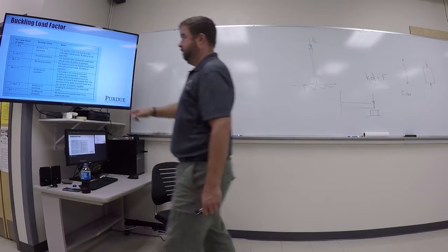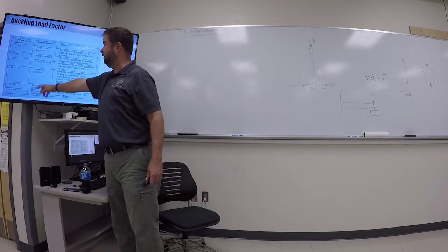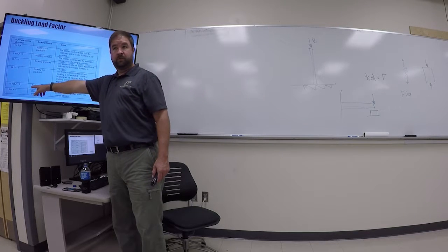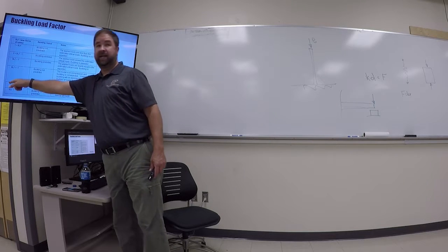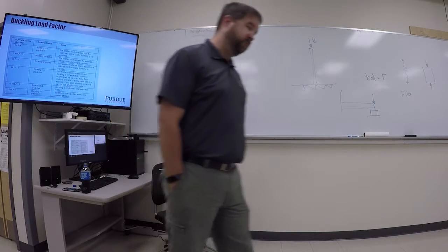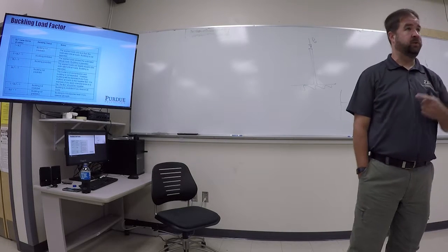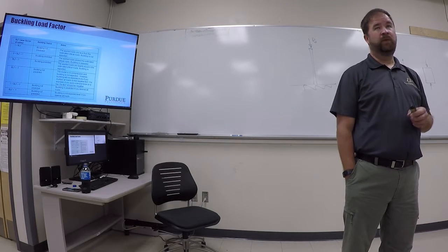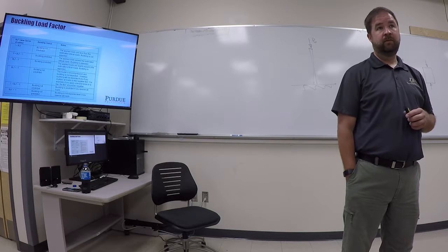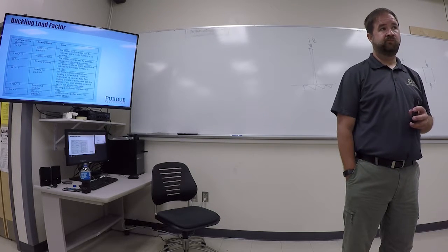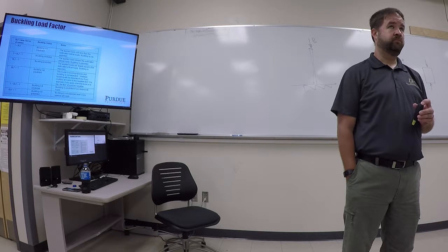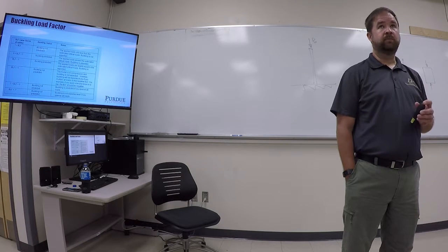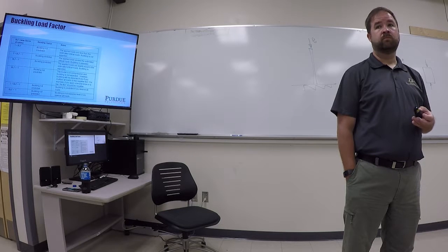And then the rest of this table is the opposite of this with negative numbers. So now if the buckling load factor is between 0 and -1, then buckling is predicted if the loads are reversed. And why would I be interested in that? Well, if it's the pressure thing, you had a high pressure inside instead of a low pressure. Or if the load's cycled somehow.